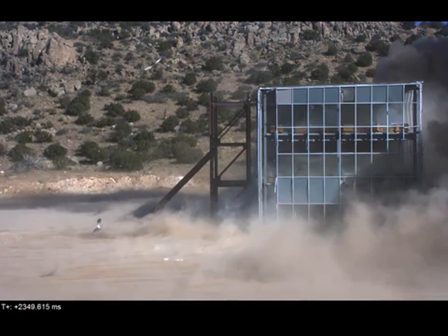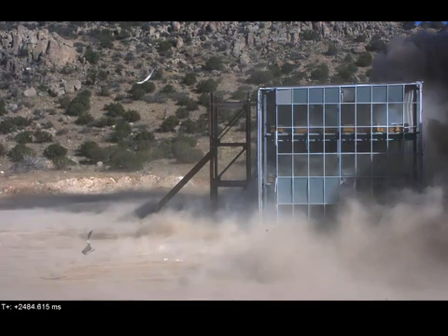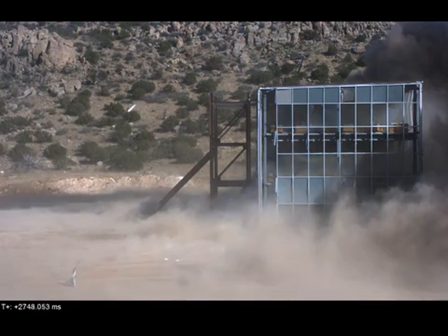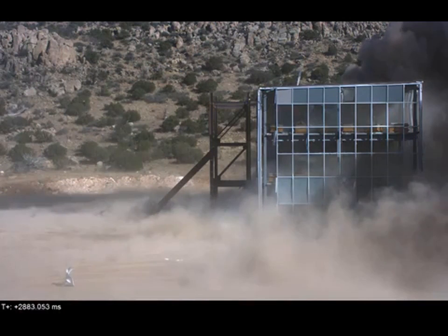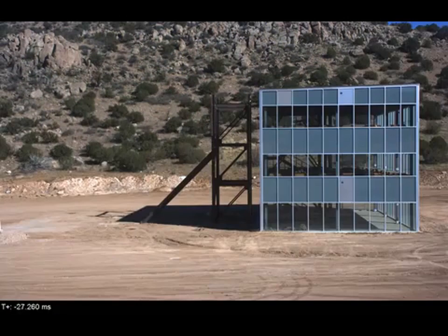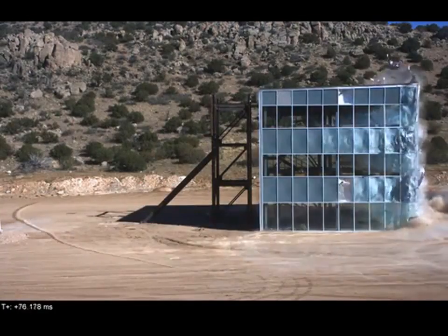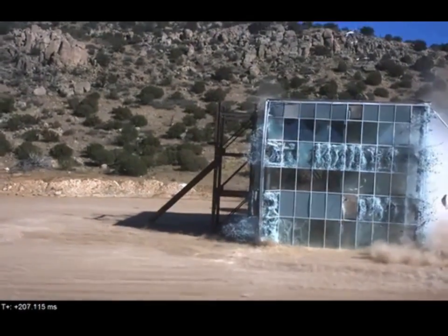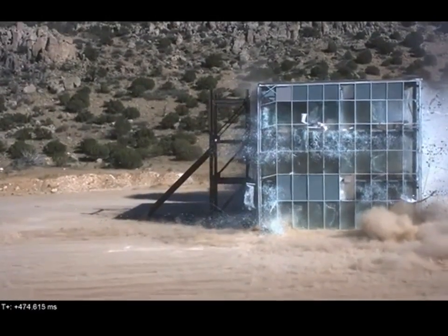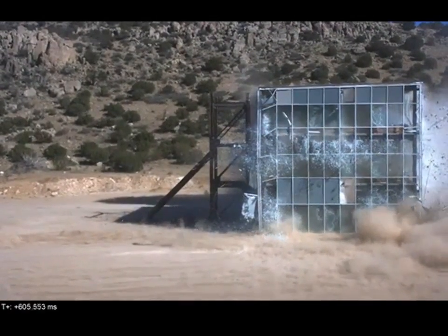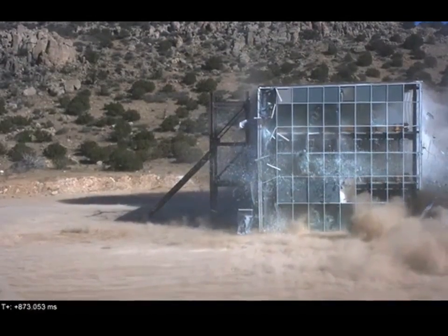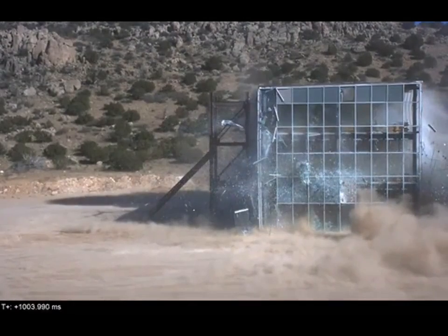We look at the building on a component by component basis, and once we look at one component, we further simplify by only focusing on one mode of response. So I'm going to play the video again, and you can keep that in mind as you see the blast wave propagating. It breaks the facade, it's going through the building, so the columns, the braces, they're all getting loaded in different directions. And when we analyze those elements, we're going to simplify at the component level, and in addition to that, we're going to be focusing mainly on the flexural mode of response.